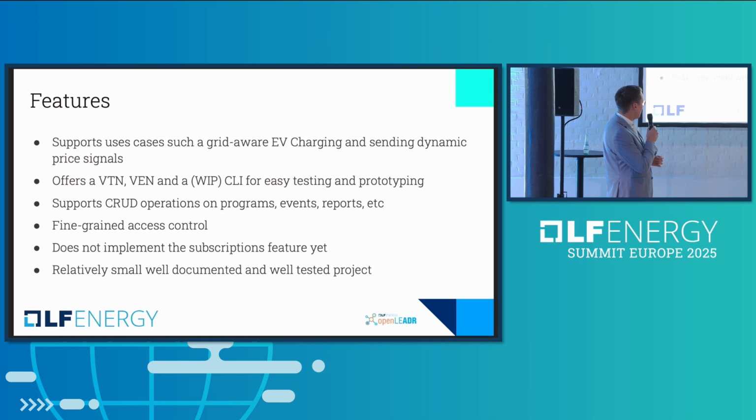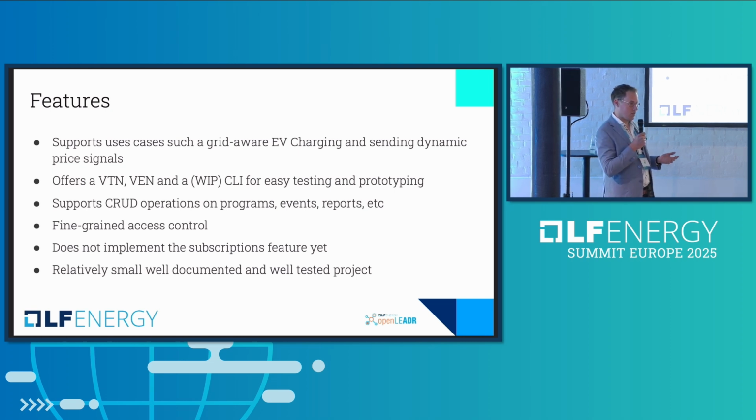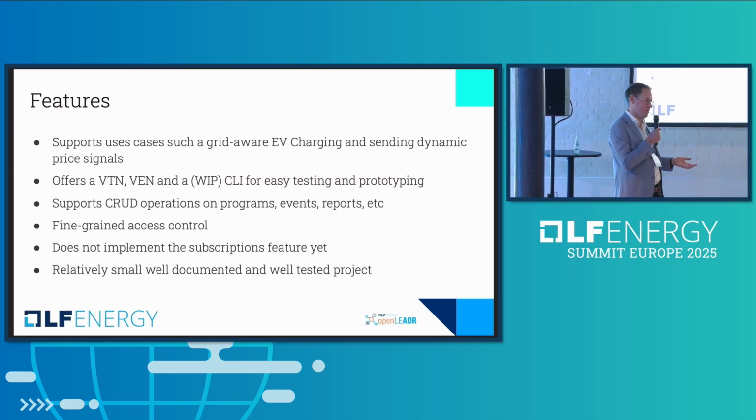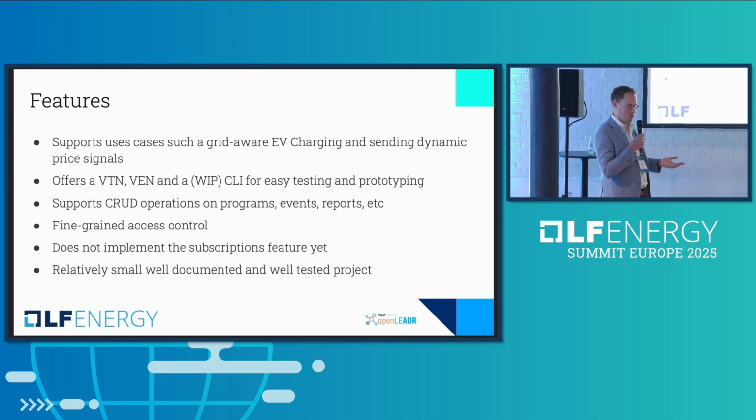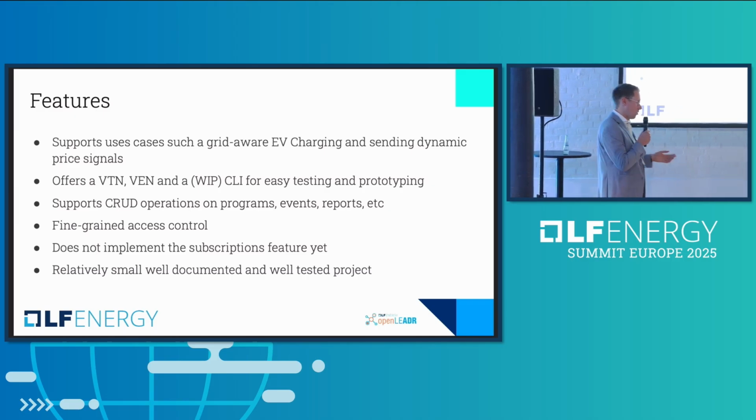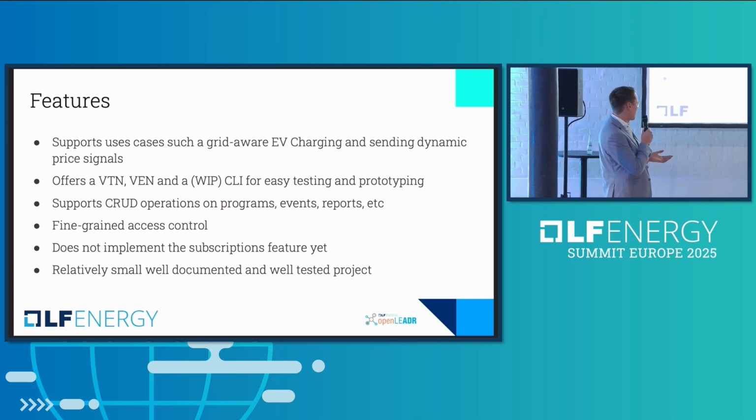Specifically, this implementation that we built together offers a few additional benefits. The OpenADR Alliance is very much about open, and they just provide the very big PDF file of the standard without the actual implementation. So while implementing, we found that you need more fine-grained access control, because you have some sensitive information. For example, CPO parties receiving information should not be able to look at each other's profiles. So we put in some more fine-grained access control there.